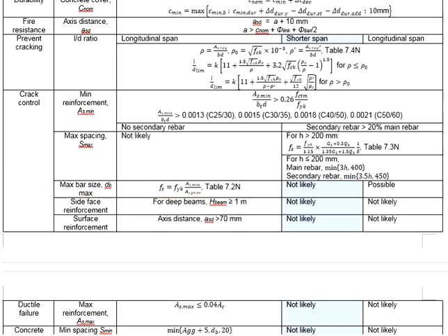As for the slab and the staircase, theoretically you should check them as well, but they are not likely to be that critical due to relatively low loads acting onto those members as compared to their effective cross-sectional area.